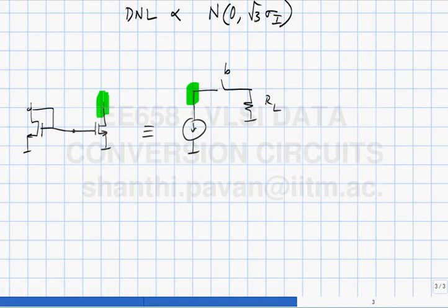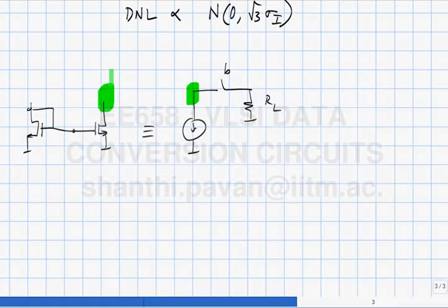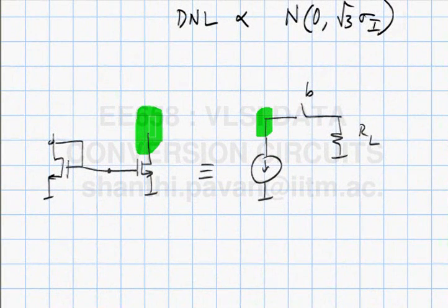Right, you could be doing that. So any guesses on what the problem might be? See, anyway, there's always going to be parasitics at this node, right? So when you turn it on, this node voltage will again have to charge up from 0 to some value, and in that process it is not as if, when you turn this on, it instantly becomes a current source. This transistor becomes a current source only when VDS is greater than VGS minus VT.